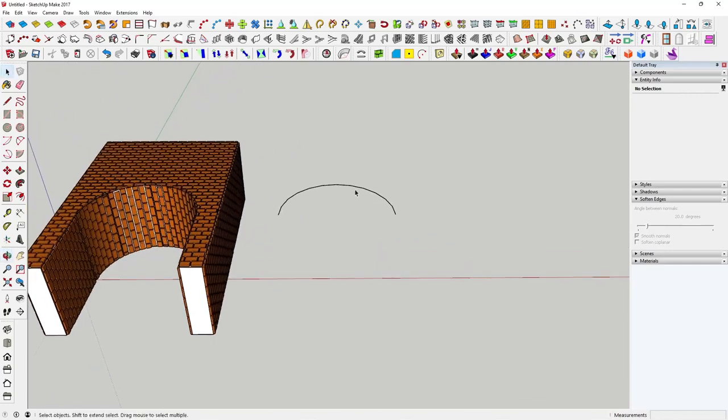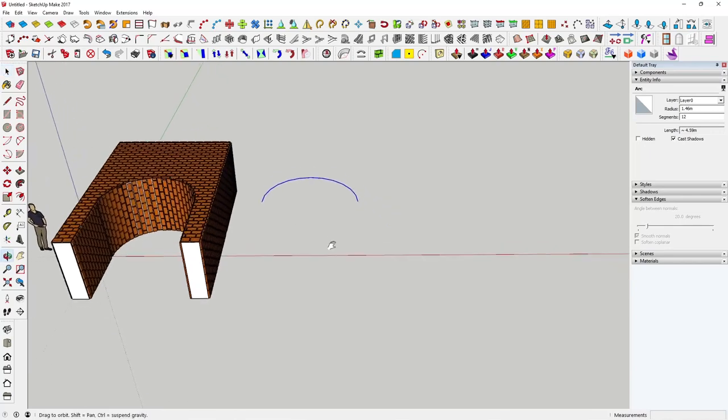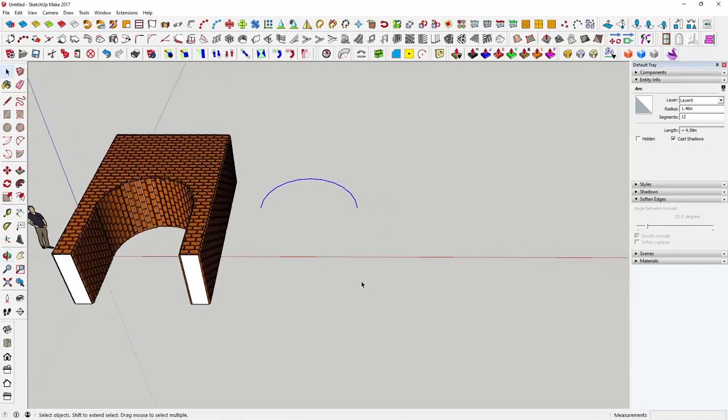Just makes life easier. Right, we'll use the arc. We'll put some soldier bricks, I think they call it. So right, rectangle tool along the bottom here. Now the length we know of that arc is highlighted is 4.59. So it's 4.59, comma, we want the height of our bricks, normally about 3, so we go for a 6. Wrong, 0.6. 4.59, comma, 0.6, and there we go.